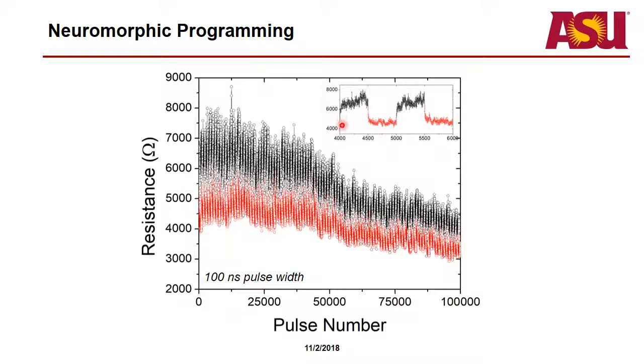But essentially, starting from a low resistance state, you see an increase in the resistive state as you're slowly erasing it. There is some noise associated, but on average, you essentially are erasing it. And then you get to some point, in this case 500 pulses, and then you reverse the amplitude of the pulse, and now we're programming it to a low resistance state, and then erasing it, and then programming it. And for this test, we did 10,000 cycles.